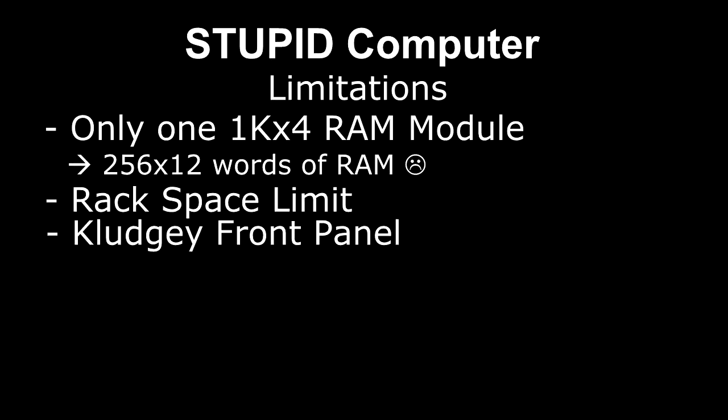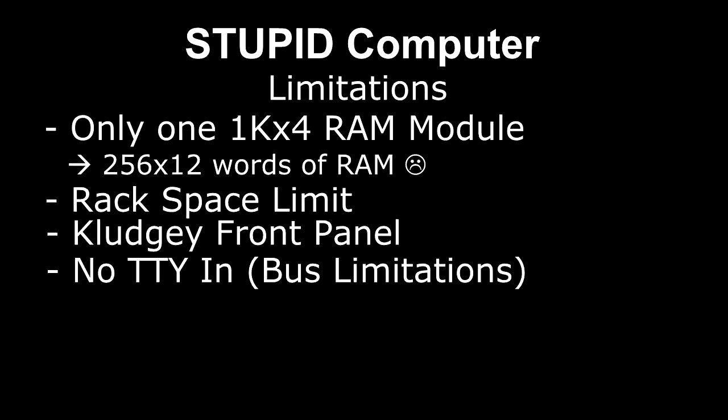Start, continue, stop, reset, your typical front panel switches. Well, I didn't have all that available to me, so as we'll probably see later, if I decide to show it to you, I had to kind of work around that. The other thing is I'm limited in the number of registers I have, partly because these buses that are shown in the block diagram are actually implemented as multiplexers.